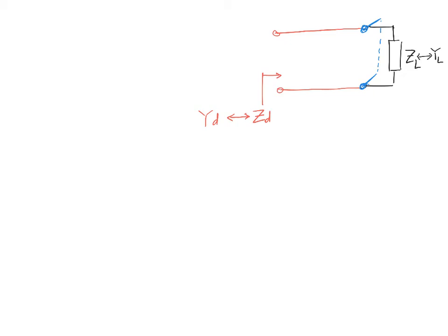And then I have only the parallel part. So what I'm doing here is only for the parallel part, without being connected to the red line and without being connected to the load. That parallel part by itself, the blue one only, disconnected from everything, will have an impedance called Z parallel, and its corresponding admittance is going to be Y parallel, which is equal to j something. So it's pure imaginary again.